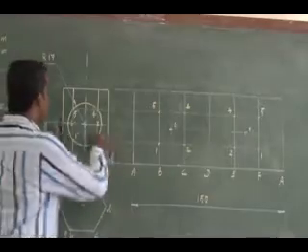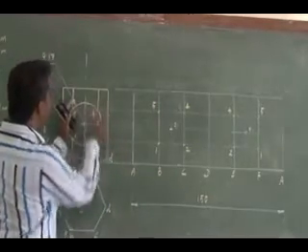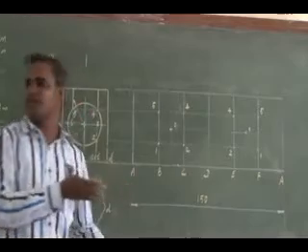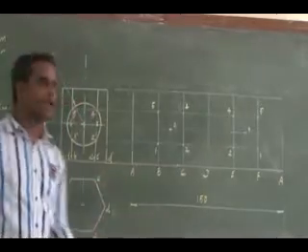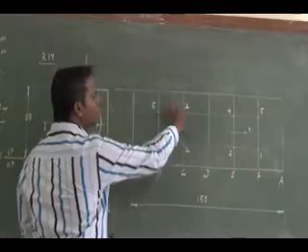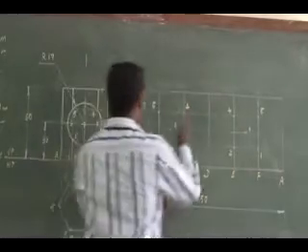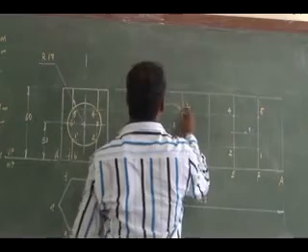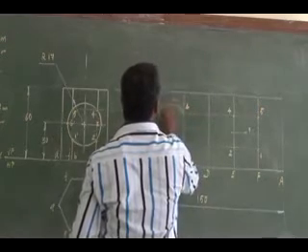Now what I can do to show this arc alone: it is a constant arc. Since it falls on a parallel surface, using a radius of 17 and this as center, from 5 to 4 I can draw that arc.